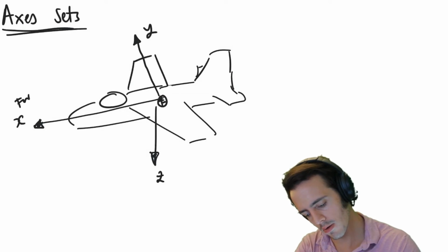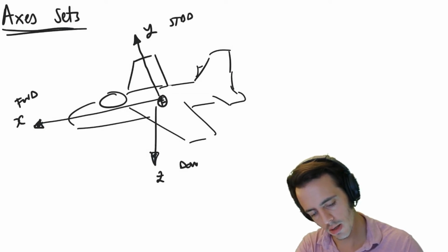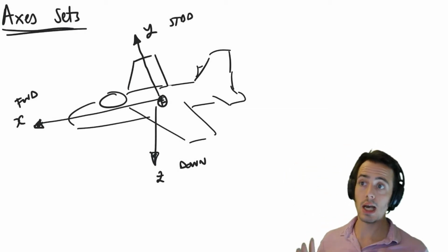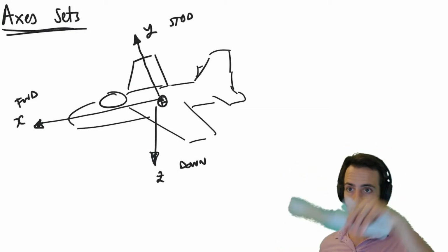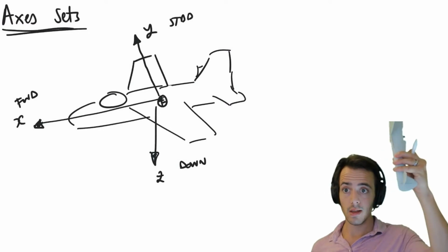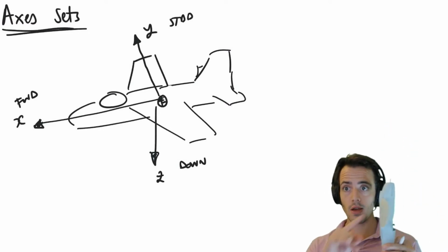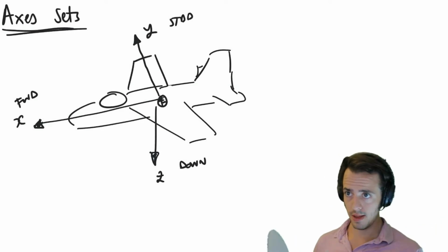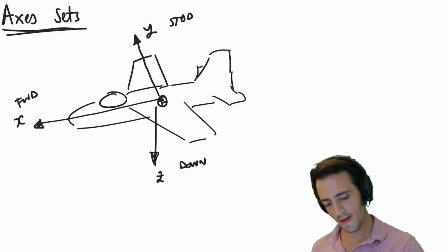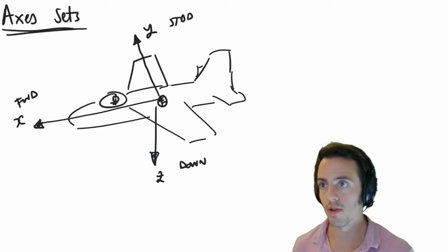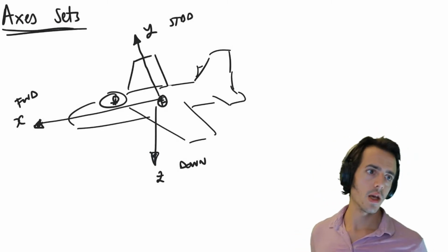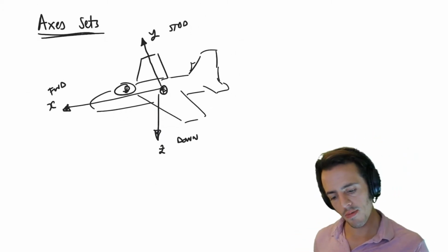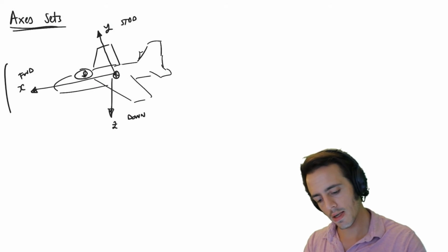There we've got forward, starboard, and down. Okay, or down in terms of our aircraft axes. So if our aircraft is climbing vertically, then the Z direction is facing out this way now. So it's no longer just down in terms of the other axes. So we've got a person in there as well, just for good measure. So this is aircraft body axes, which we'd already defined.